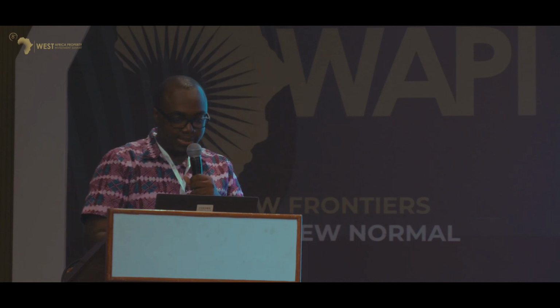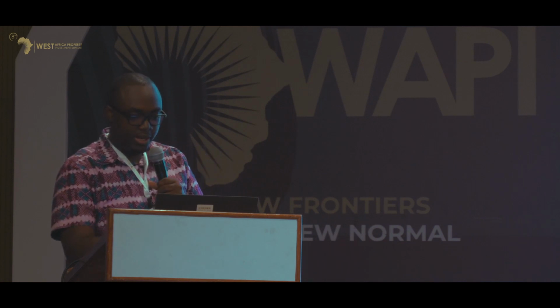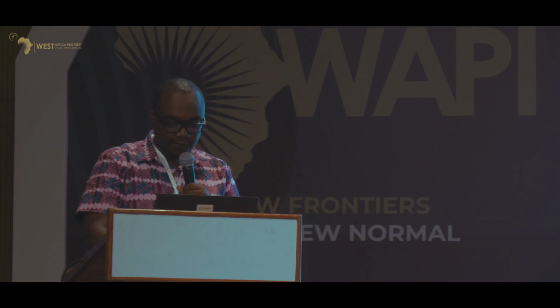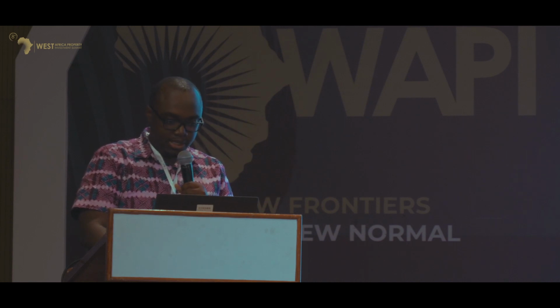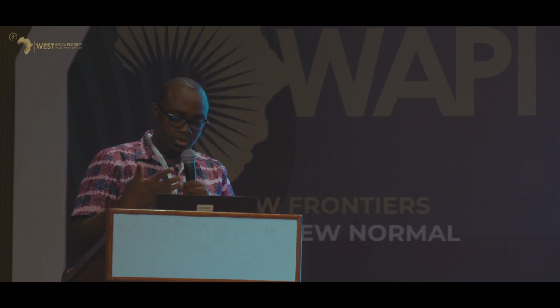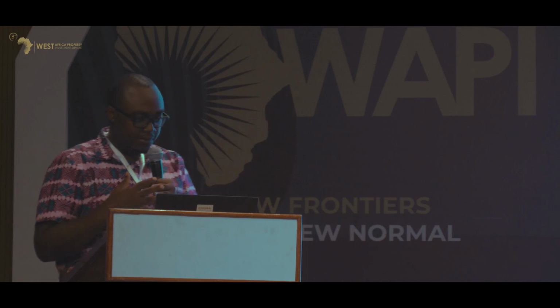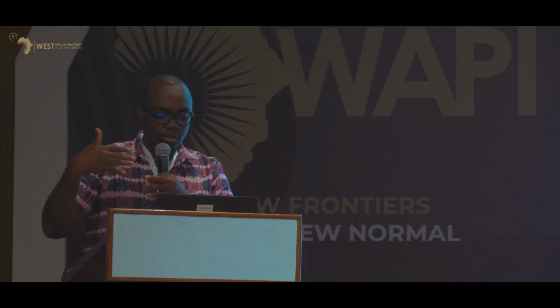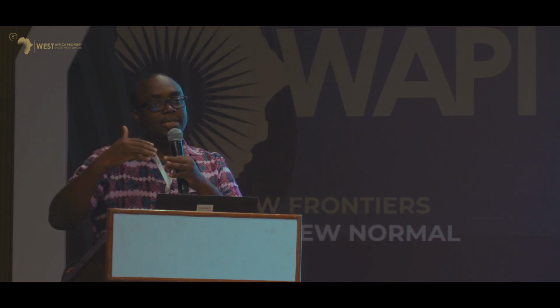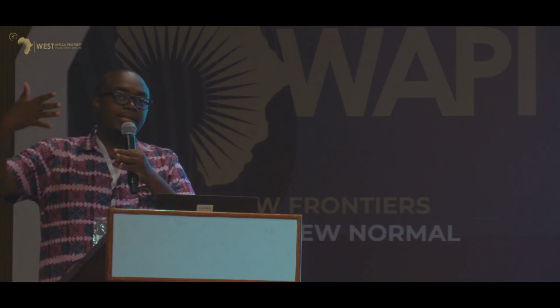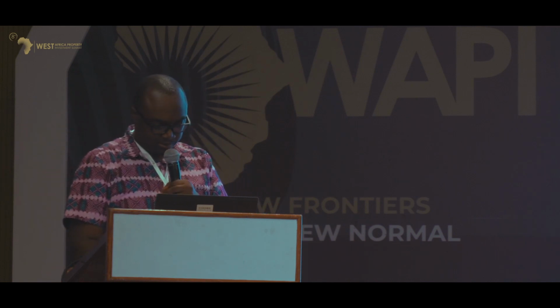So the bedroom size, 60, kitchen 15, dining area. So you are able to input all this. The living area, 30, toilet 6, utility 4. Then the building dimensions as well, the north, east, west, or as it applies to your project. Maybe you have your elevations around the northeast, southeast, or southwest. You are able to put this in the app, and the app can intelligently evaluate the heat gain into the space vis-a-vis the window to wall ratio as well.